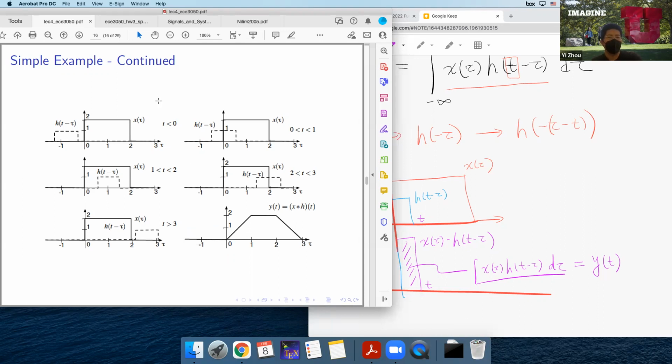So that's why we have a flat curve in the negative time domain. And now we keep increasing the value of t. At some point, these two rectangles will start to overlap. Increasing the value of t is equivalent to moving this smaller rectangle to the right. And then that will generate a non-zero convolution value.